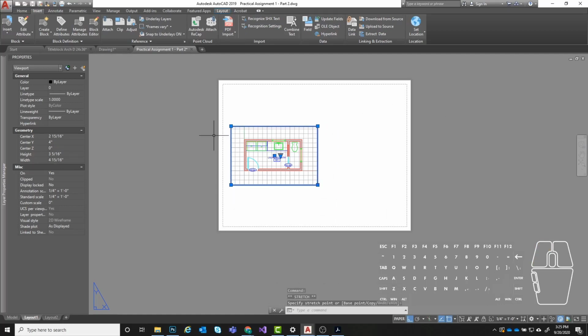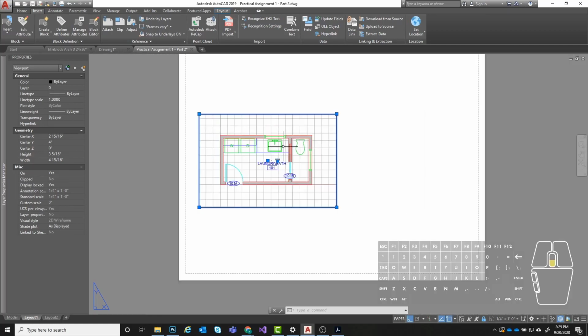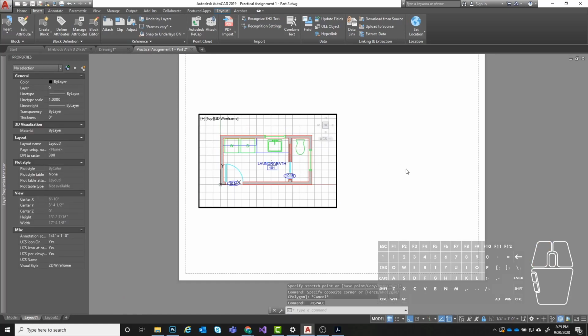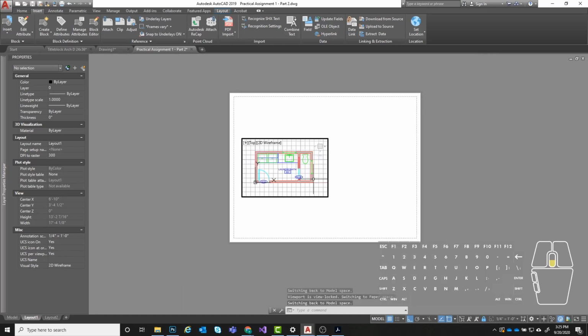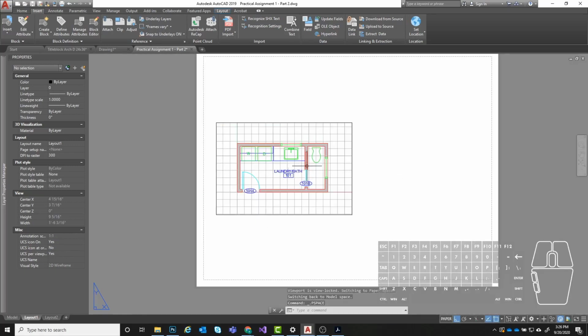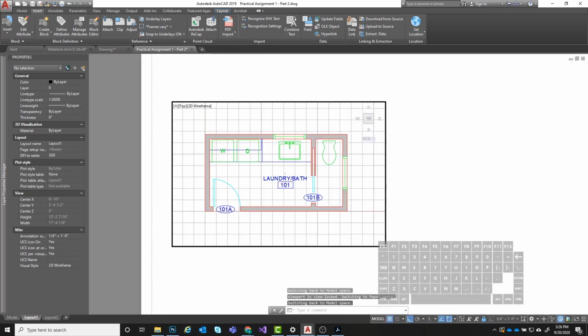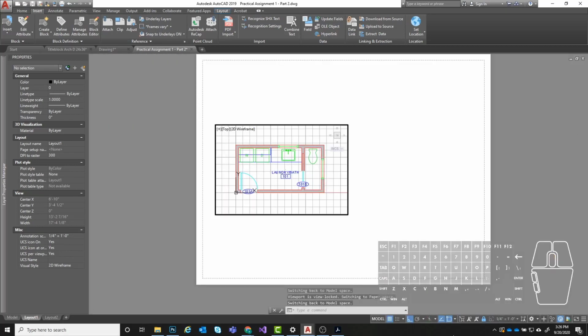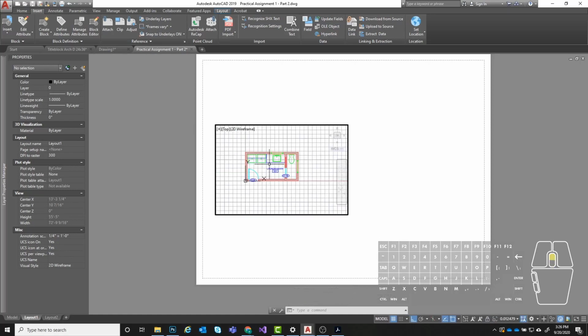And then once you have that, if you are set on your scale and you have it exactly as you want it, you want to go ahead and click on this lock button right here. All right, when you click on that, you can no longer modify the zoom of the scale. So when I double click to re-enter the viewport, right now I'm in model space. You can see that right here. So if I do that again and double click inside of that, when I zoom in and out, I'm no longer zooming within the viewport. All right, so if I turn that lock back off, for example, now I can freely zoom in and out, but you can see my scale gets messed up again.